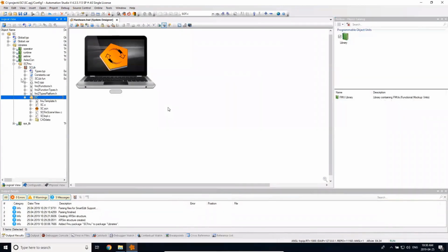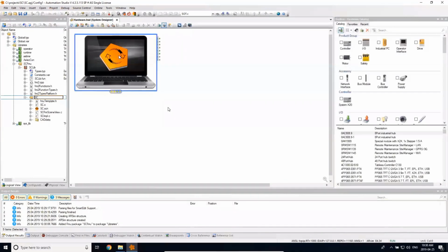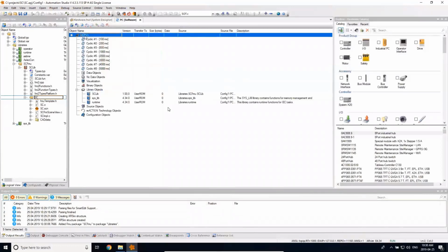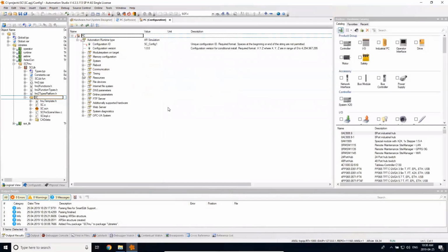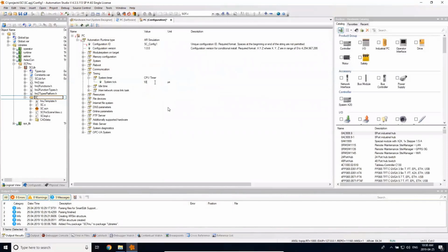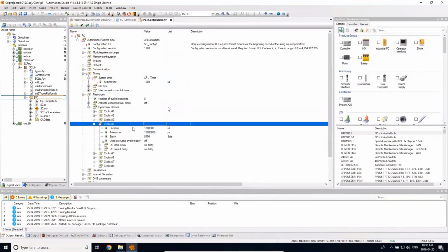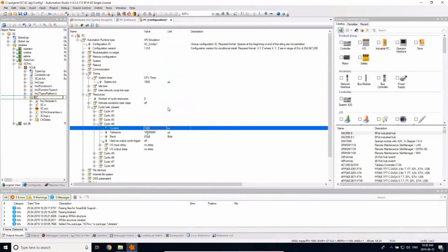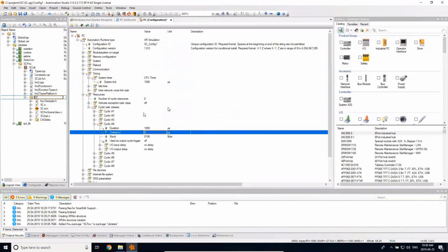So let's set up a program. Let's get this running first, and then we'll go into Scene Viewer to see it in action. And just before I forget, I'm going to update some of my system properties. This is so that the communication between the FMU I generated and the system and how it's running are going to sync up nicely. This time that I'm using is just the communication step size that I would have defined in the B&R FMU generation tool from MapleSim, and this is the task class time.